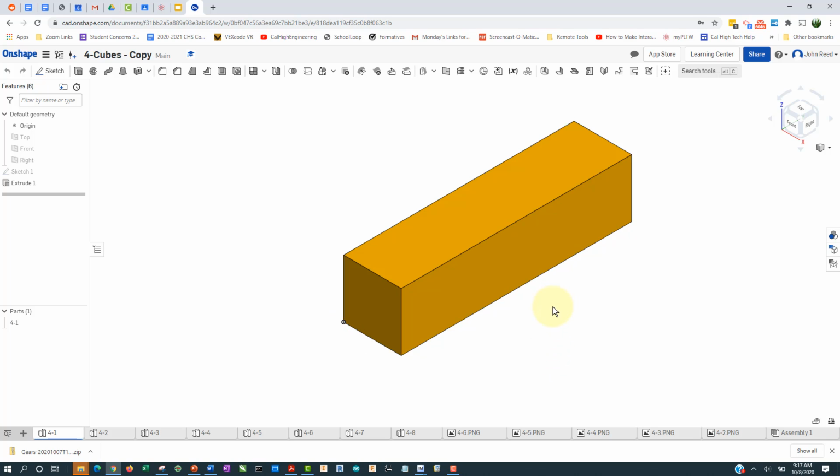So we're going to have to select a different view and or rotate the part when we place it in initially. So the right, top, left, or bottom view, any of these long views, we want to be the front view in the drawing.